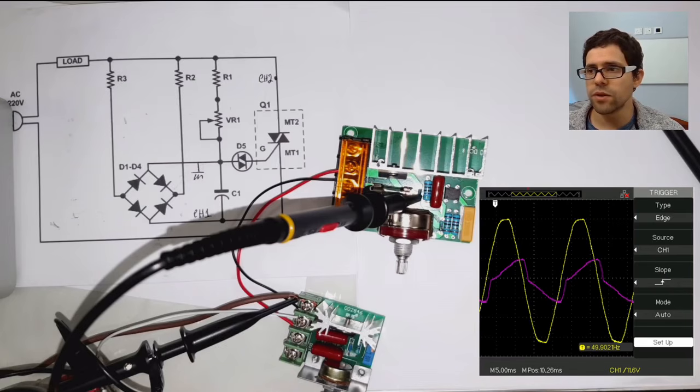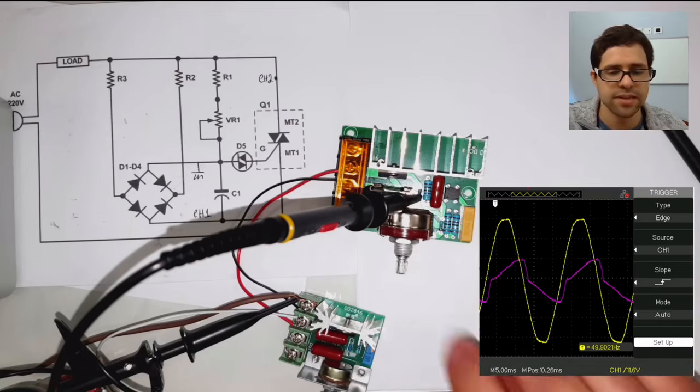And then once the voltage reverses, not much happens, but when we get to the 0 cross, suddenly the capacitor is discharged. So we have this much faster slope than we had to charge. And so when we go into our negative half cycle, we're very much at this ideal condition, which is 0 volts across the capacitor. So bingo! Now I don't have to worry about discharging the capacitor because the diodes and the resistors have done that for me. So how brilliant is this?